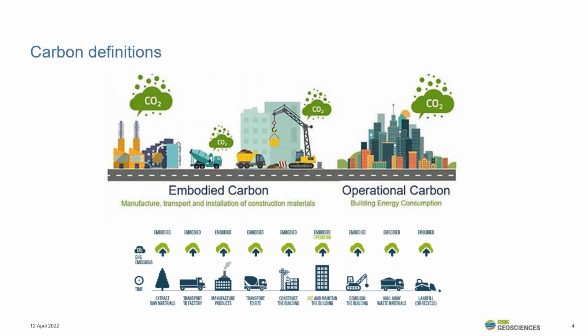It includes any carbon created during the manufacturing of the building's materials, so that's materials extraction, transport to manufacturing, and then the movement of those to the construction site and the construction practices themselves. Put simply, embodied carbon is the footprint of a building before it becomes operational. It also refers to the emissions produced maintaining the building and eventually demolishing it, transporting the waste away and recycling it.